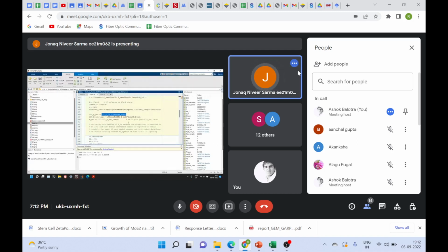There are some intricacies, but we can safely ignore some zero padding kind of issues. And this FFT, then IFFT shift, FFT shift up top, these are just because we want the continuous time Fourier transform, but FFT gives results in a weird manner.